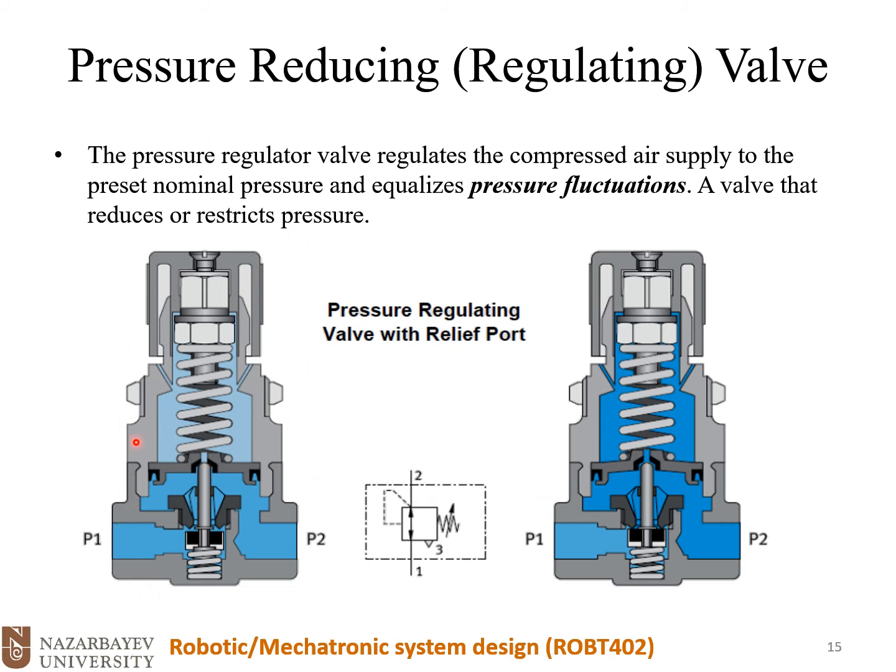It's not designed to increase the pressure from 1 bar to 3 bars. It's just designed to regulate and equalize the fluctuation. Let's say it could affect the air pressure by plus or minus 0.2 bar.